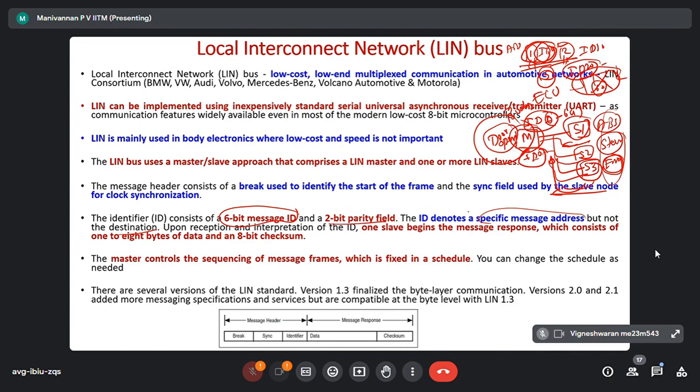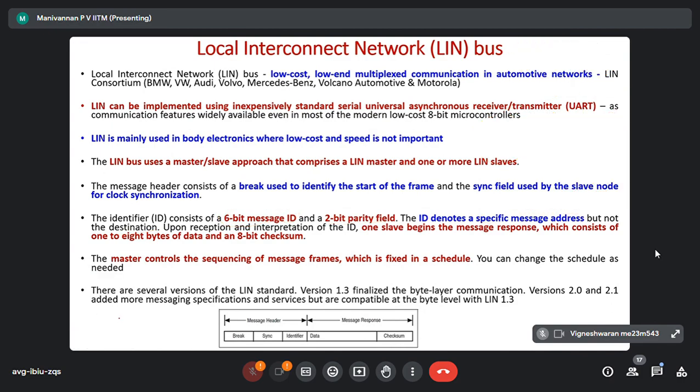Here, in LIN bus, data is sent as master slave. Only whenever the master asks for data, the slave should send. Otherwise, you cannot send any data. The slave should just keep quiet. He cannot volunteer, I am sending data, please receive. That's why I said, you cannot go to your company CEO, sir, I have data, I want to do this. But generally, there's a provision.